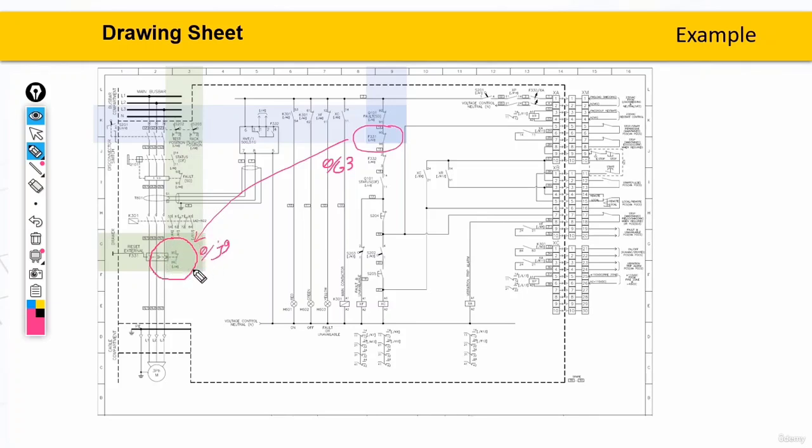So guys, in these sheets, we would basically see some symbols, and next to them we would see some addresses consisting of letters and numbers, which would work as some sort of a referral, you can say. Now, there's actually a name, or well, it's better to say a term used for such phenomena. When the equipments are referred to each other through their addresses, we call such phenomena cross-reference. And by the way, guys, remember, if you are using some specific software such as ePlan, for your works and projects, you should know that such things like this cross-reference will be done quite automatically for you.